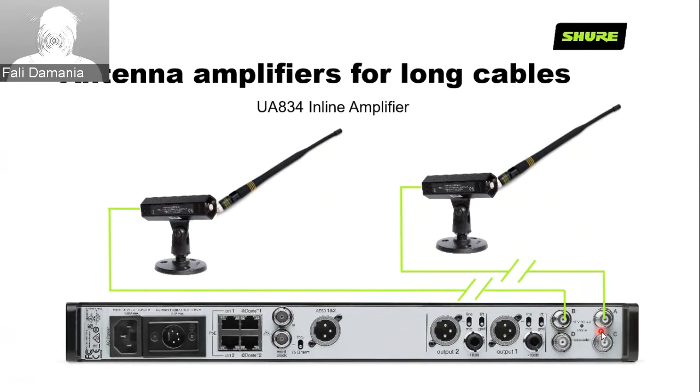They also have an overload LED indication. So in case you're hitting it with too much power, there is an overload light which will come on. When I say too much power, I mean on the receive front. In case the receiving end is overloading the amplifier, then that red light will go on, and it's an indication that your receive power is too high.